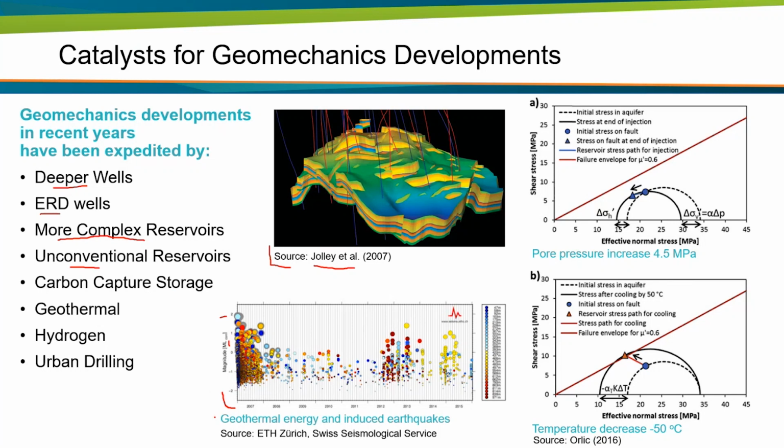So these kinds of projects, geothermal and CO2 injection, and projects near urban areas, will require more studies in order to make sure that all of this is done safely. For instance, we don't want CO2 leakage into a shallower aquifer when we inject CO2 and want to store it for a long period of time. And so a geomechanics study is required in order to avoid fault reactivation and fracturing.